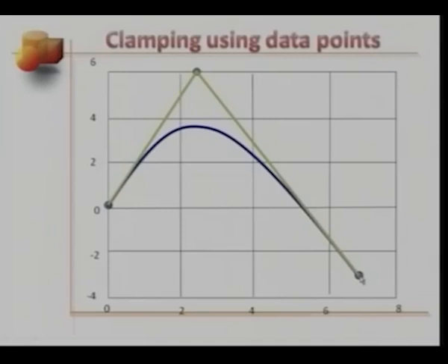Now, if you bring this one here to coincide with this one here, and imagine that if you had another design point somewhere here, maybe, so that you could have made 1, 2, and this one here collinear, then you would have expected that the curve not only would it have passed through this design point, it would also have been tangent to this control point line here.